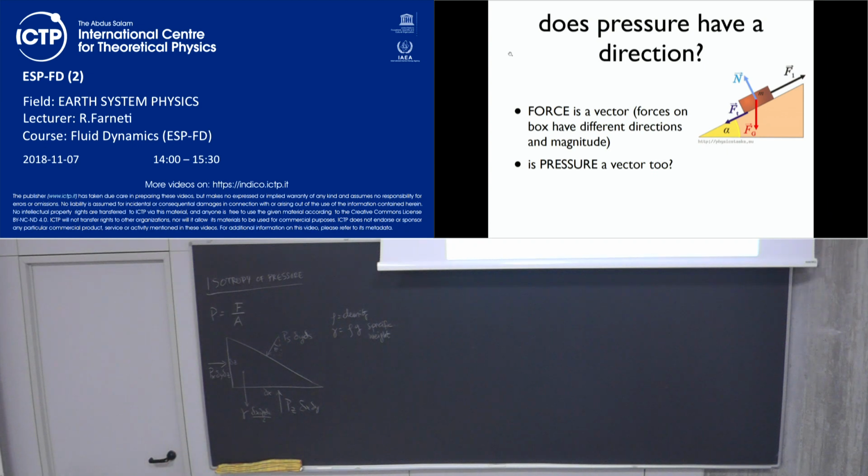Okay, so in a static condition, all the forces in all directions must be equal to 0, or must cancel out. So just remember that here, delta x is delta s cosine of the angle theta, and delta z is delta s, the sine of theta.